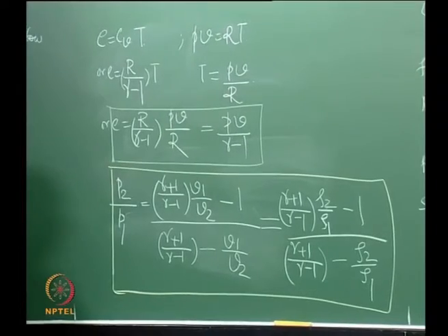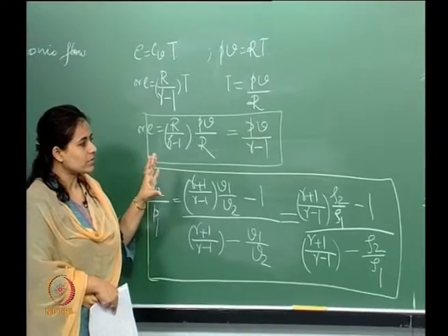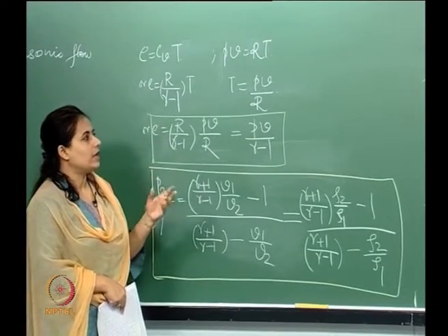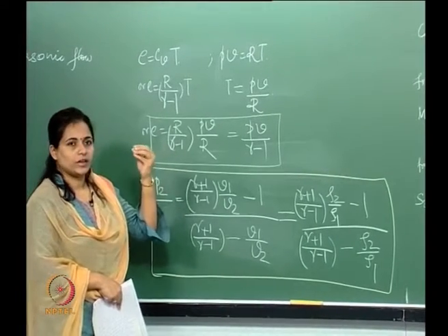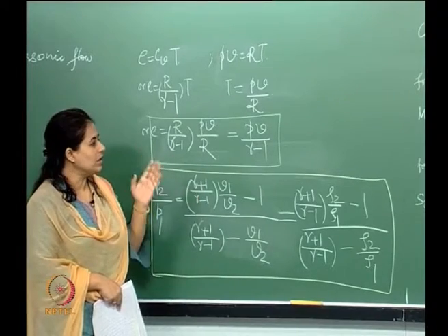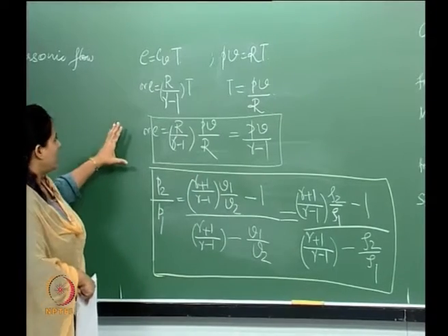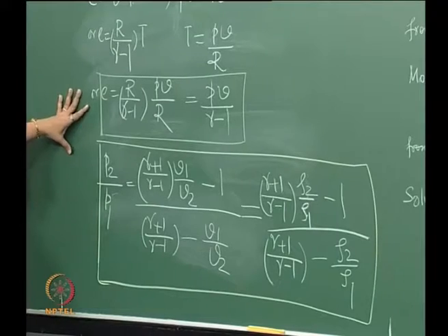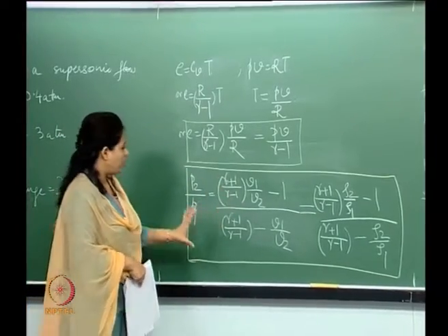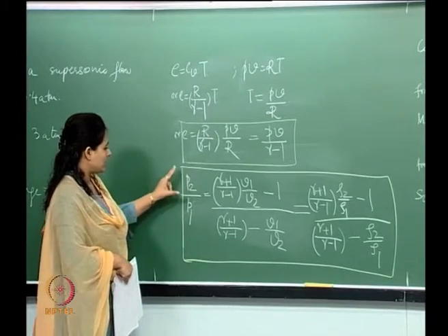Okay. So, what we have done is first we wrote out our basic equations of flow governing a normal shock. Then we got rid of any velocity terms using the 3 basic governing equations, and we came up with the Rankine-Hugoniot equations. Now, in the Rankine-Hugoniot equation, we did some more manipulations and we came up with this sort of a relationship. This is a very interesting relationship, because if you see what this is telling us